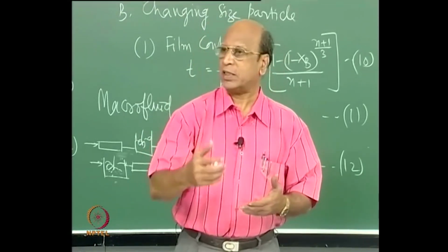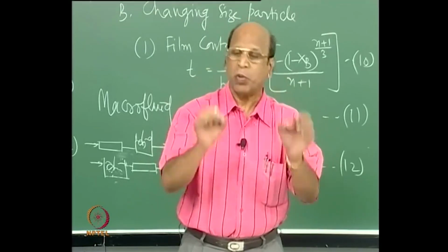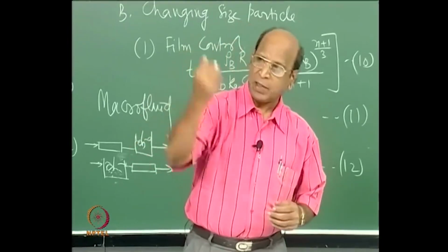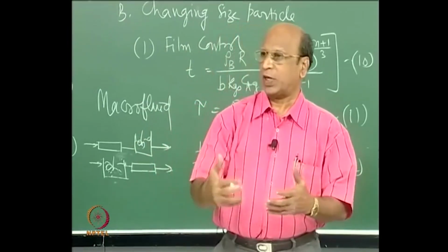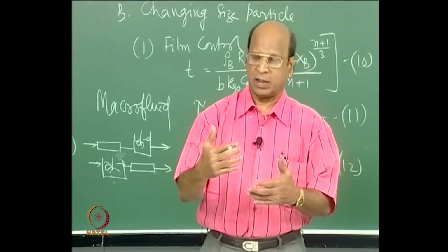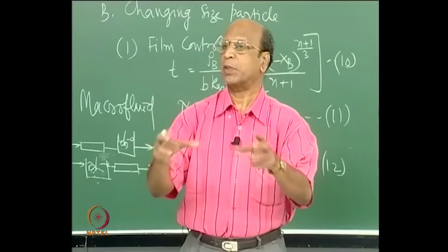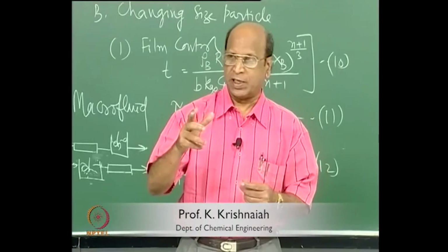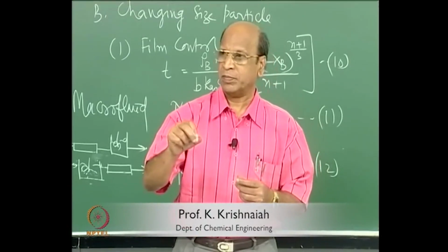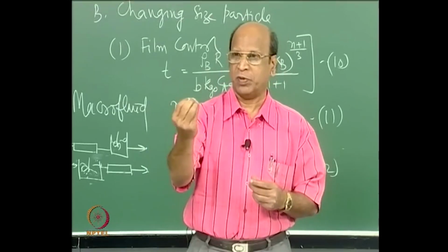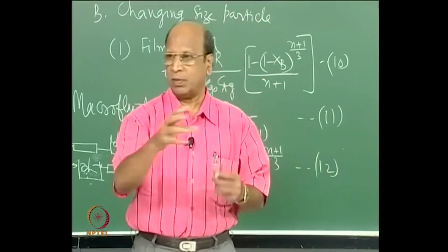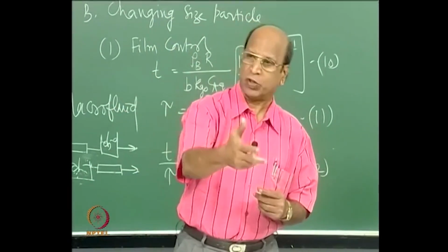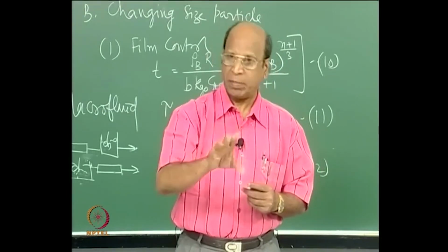And the other extreme is the microfluid, where we have individual molecules freely moving throughout the reactor. That means, if there is a chance for reaction, any molecule can react with any molecule, because there is perfect mixing. Perfect mixing is possible in a microfluid. You should not get confused here, but even for this microfluid, there are two restrictions. One is the status of the fluid itself: fluid can easily move in the form of individual molecules, so there is a possibility for the molecules to interact with any molecule. But that is one restriction.